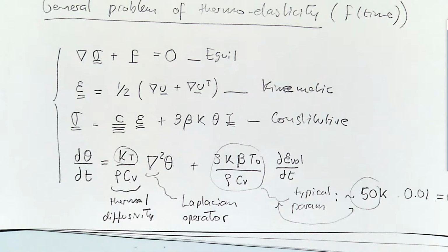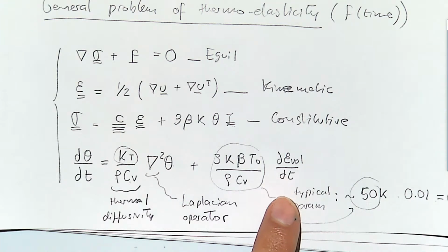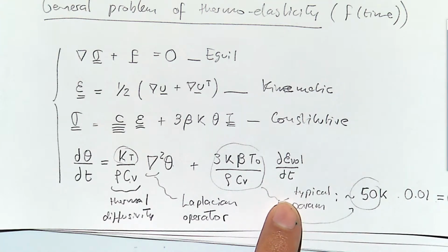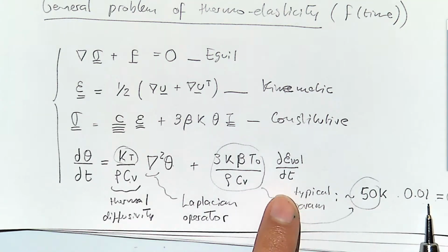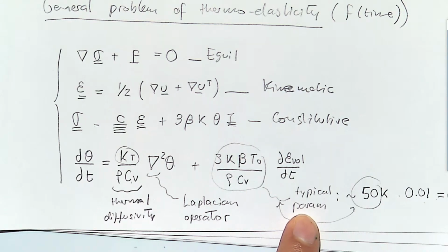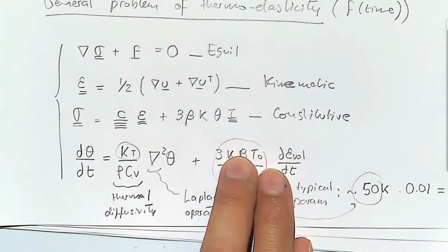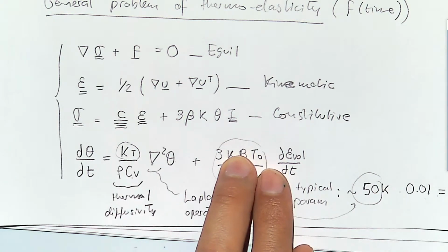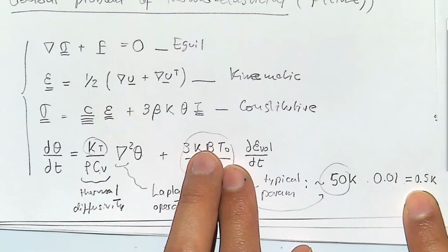So it's not like, for example, in poroelasticity, where a change of strain of 1% would give us a very high pressure in undrained conditions. In this case, you can have huge strains, and 1% is quite large, and still have a very mild change of temperature. So sometimes you can neglect this term. Or sometimes you can do a coupling which is not fully coupled: just solve the heat part and then solve the mechanical part without taking this term into account.